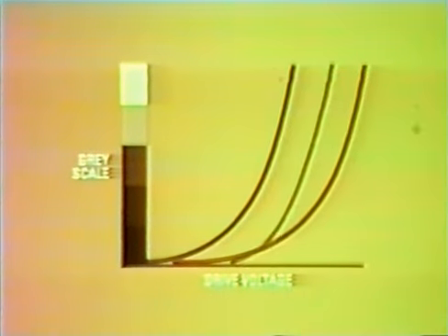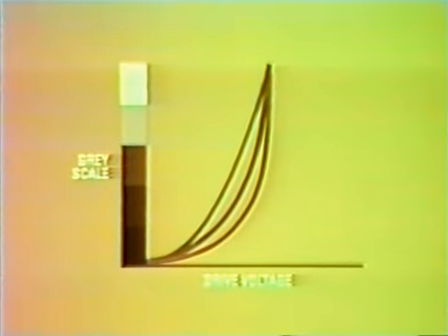Manufacturer's instructions should again be followed exactly, a typical sequence being to align the cutoff points for the three guns, then by proportioning the drive voltages to obtain illuminant C at peak white and as far as possible over the whole gray scale.